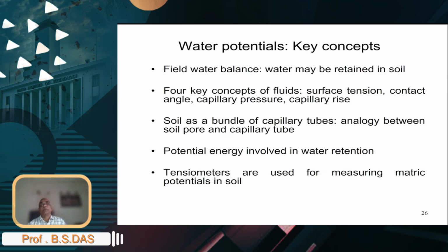Then, of course, we talked about how water moves, in terms of the driving force, and we were able to link that to the potential energy, and we introduced the concepts of soil water potentials, four different components we recognized, from gravitational to pneumatic. Then we described how the total potential concept and the hydrostatic equilibrium are nicely bundled together into a very simple device to measure soil water potential.